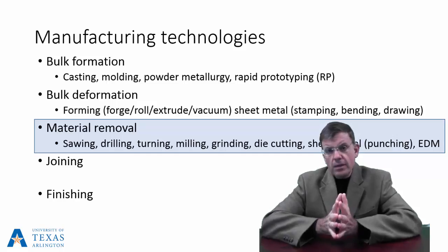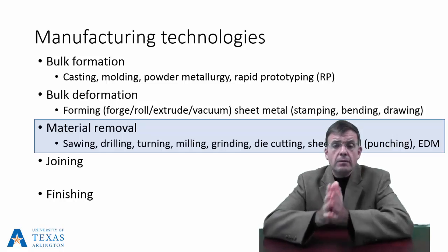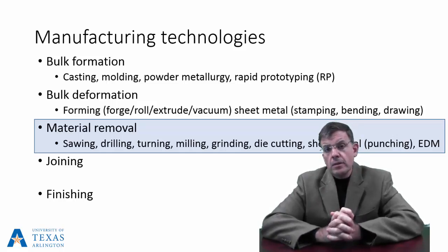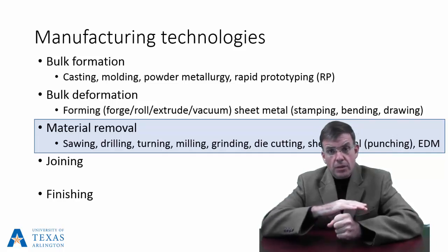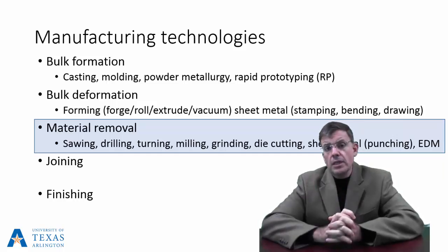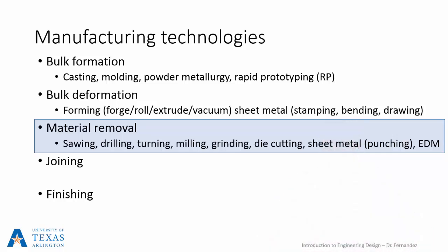Grinding in this particular context is used for material removal, particularly for metals that are very, very hard. So for high performance metals, where it may not be expedient to use conventional cutting or other material removal processes. Grinding, of course, can also be thought of in terms of achieving a smooth surface or removing burrs. And then at that point, grinding transitions into a finishing process, which is a whole different ballgame altogether. Now we're talking about very, very high precision working of a surface.